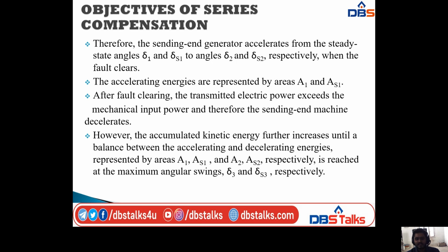After the fault clearing, the transmitted electric power exceeds the mechanical input power, and therefore the sending end machine decelerates. However, the accumulated kinetic energy further increases until a balance is reached between the accelerating and decelerating energies.